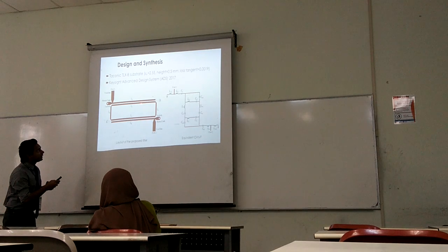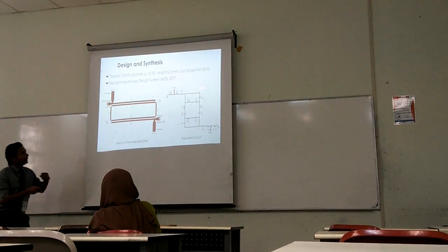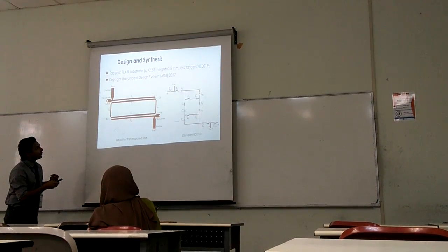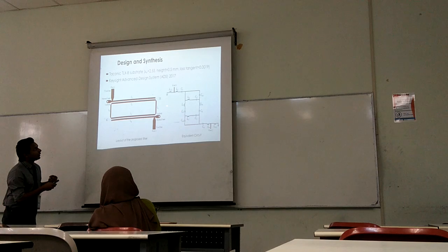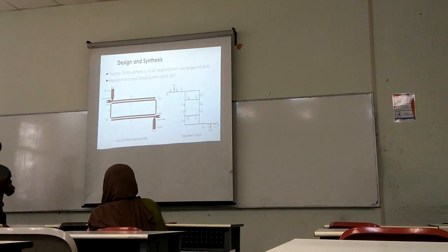And we all know that if there is an electric coupling between two comb lines, or between two lines, then there is a mutual capacitance. So that electric coupling is determined by this CM, like here and here. So this is our lossless equivalent circuit.